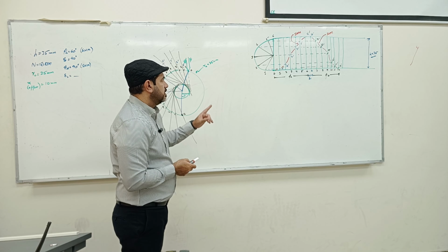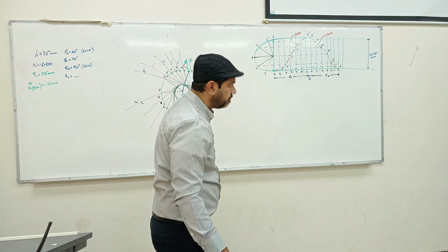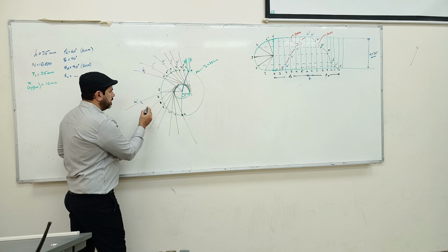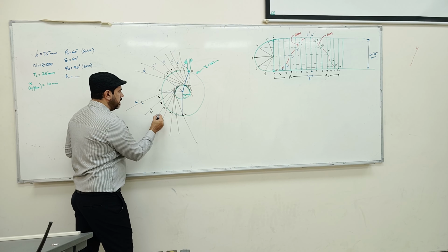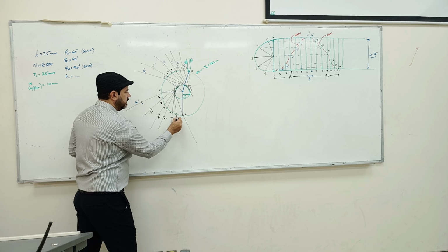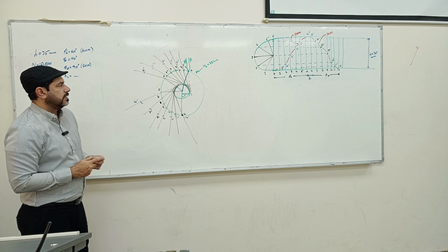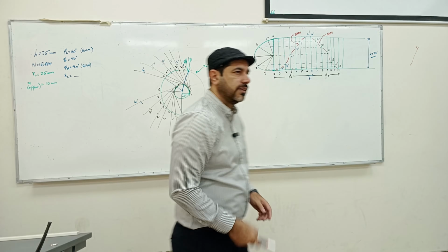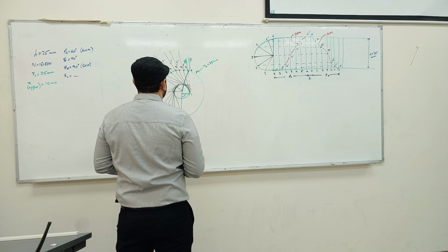Okay, understandable. So you can see the difference. Now we need to take the compass again over here. That's not a big deal anymore because we have already done it a few times. The 6 is already marked. 7, 8 prime, this one is 9 prime, 10 prime, 11 prime. Almost everything is done. All we need is to join all the points. We are going to join all the points together.